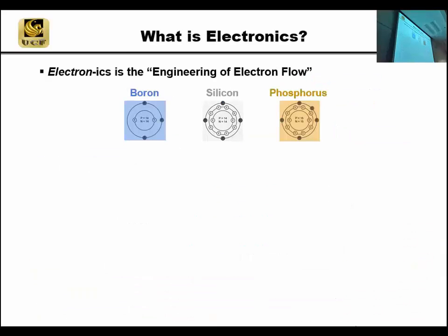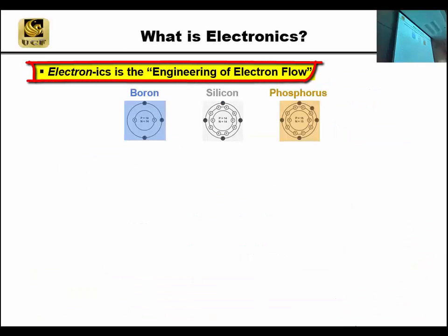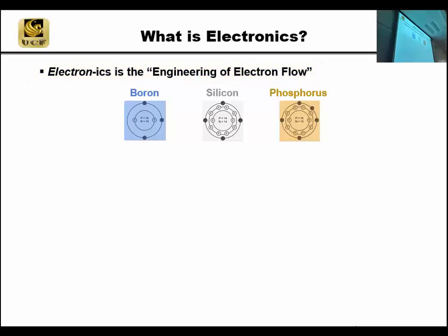Here's a cool thing. Once we know just this much chemistry, we can engineer this. So we're going to use silicon as our semiconductor, and then we're going to dope it with either boron or phosphorus. Now, back to our happy families. And this is the outer orbital. So we have 4 here. And guess what? I can add an additional electron if I have phosphorus sitting next to silicon. You see, phosphorus has an additional electron relative to silicon.